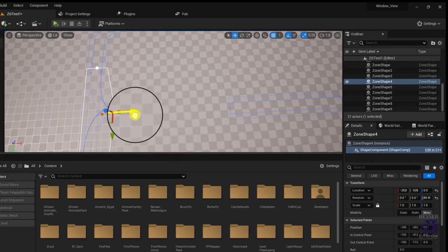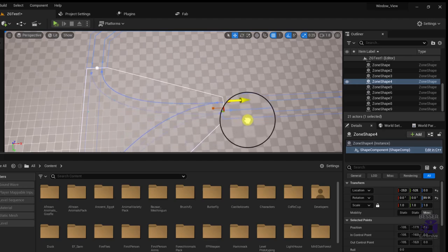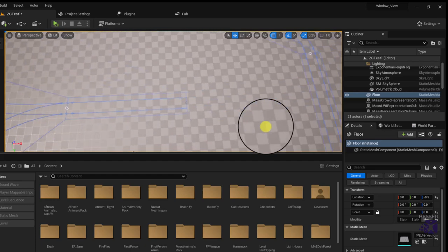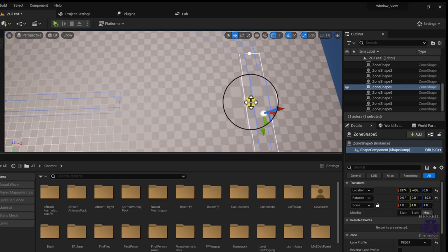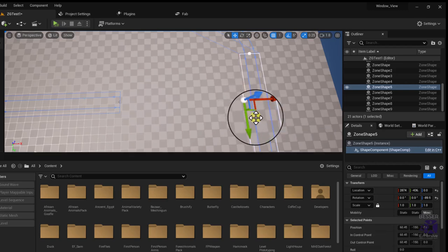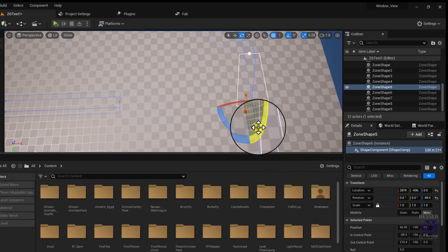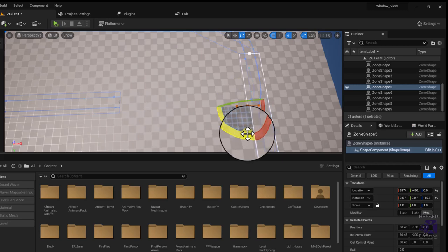How far you drag one side will determine the path. You will see the lane profile stretch as you drag it. Do the same thing with the polygon on the opposite side. Select it, right-click to add a point, change to lane profile, rotate, and drag it to connect to the piece in the middle.